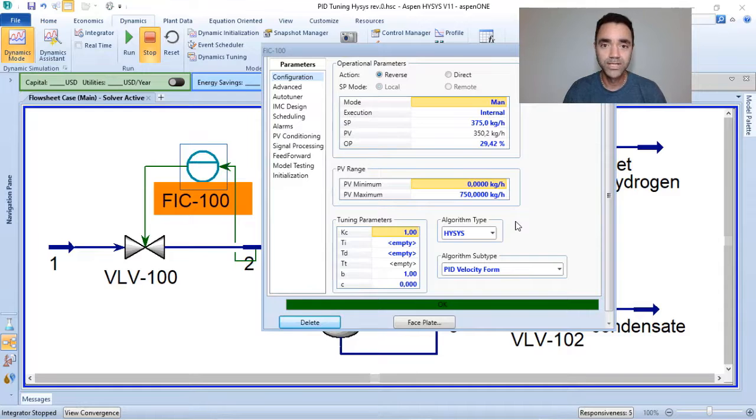It's important to understand that, depending on the controller vendor, the information that we add to the PID can change. For instance, as we have seen, the integral part of the PID can be expressed as time per period or period per time. So if that changes, the value that you need to use changes.